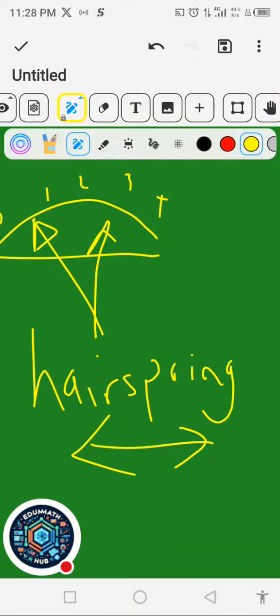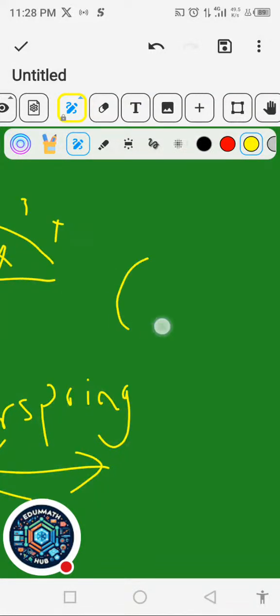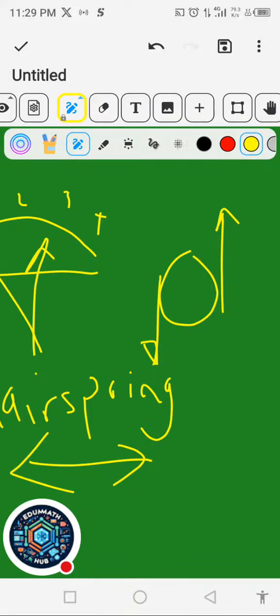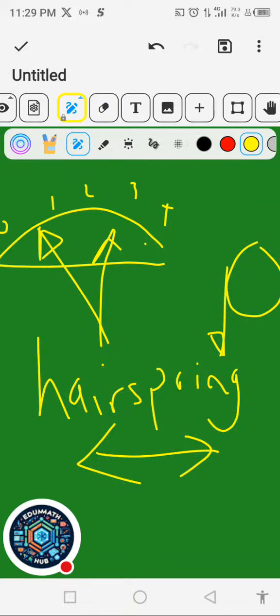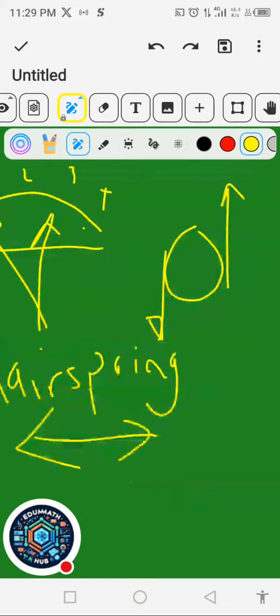Okay, so it produces something called a torque. A torque is just a rotating force. This one is going like this. This one is coming down like this. So it causes rotation, right? So that torque will pull the pointer back to where it was before. Once you detach this one, it will go back to maybe the 0 mark. When you connect it again, it will move to maybe like 3 milliamperes. If you're not using it, it will go back to how it was before. So you can be on 0 in its resting position.